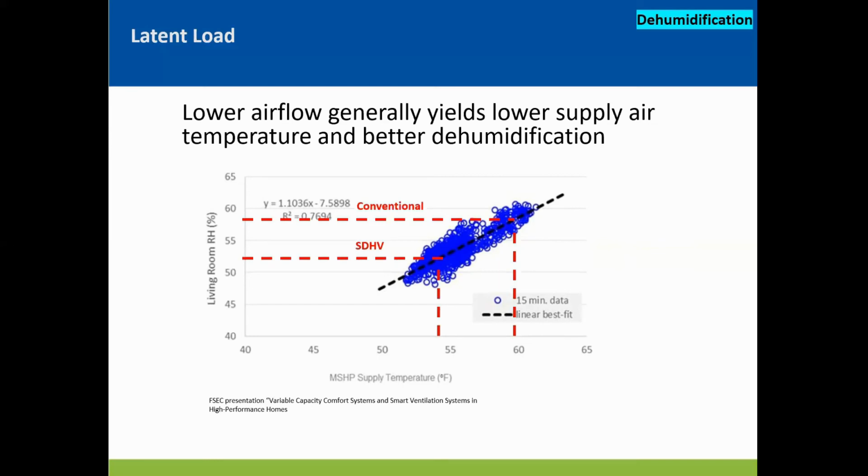Whereas a small duct system, which had lower supply air temperature, would maintain the same room at closer to 50% relative humidity. The occupants wouldn't have to change the thermostats, and any dehumidifiers that would be needed didn't run or ran for very short periods of time.